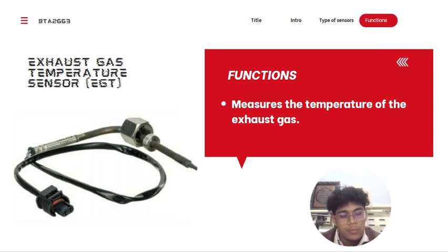They are also useful for protecting the SCR, or selective catalytic reduction, and LNT, or lean NOx trap, and other NOx absorbing systems. Although it is considered an old tool when it comes to tuning performance on racing engines, an EGT probe can still be a very useful tool that provides valuable insights into what's happening inside the engine.